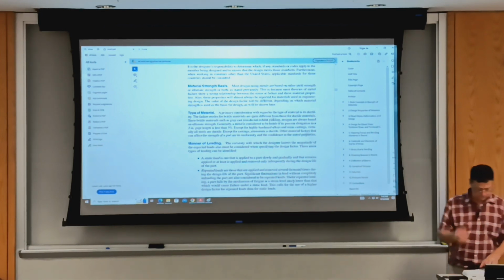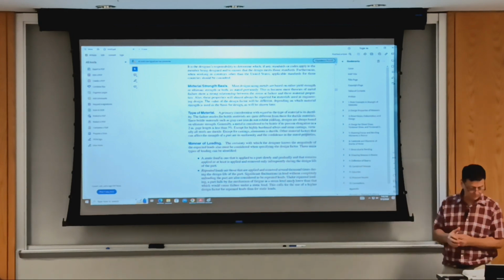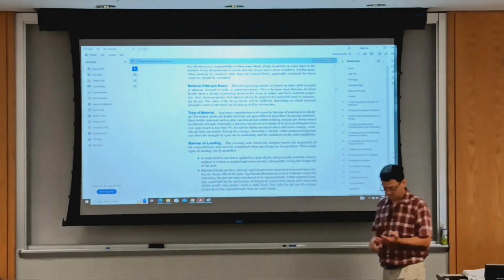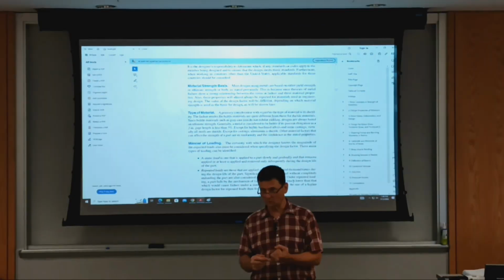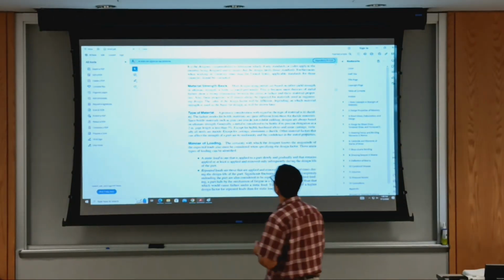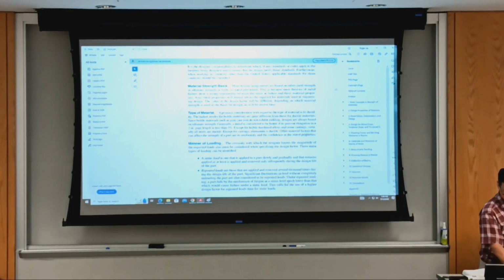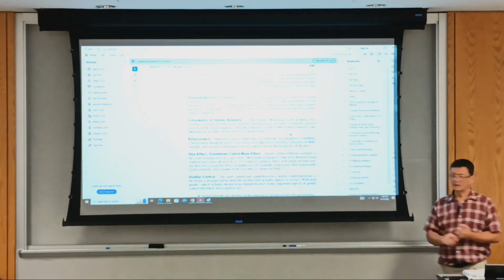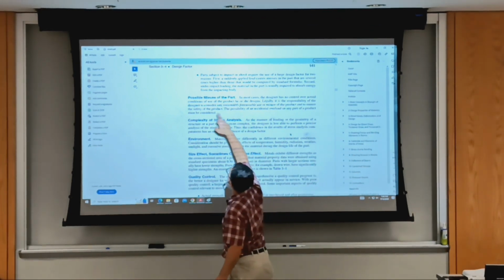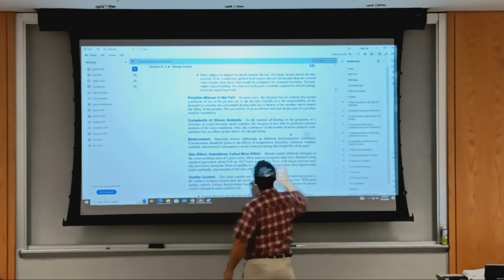And when you choose a design factor, again, you're responsible. You need to know what can happen during the life of the product and what the effect of failure could be. So a design factor captures uncertainty about the load, the possibility of overloading. Let me project the actual section. It says manner of loading, but design factor captures overloading due to misuse. You cannot anticipate that happening. It's too complicated, so you simplify the part.